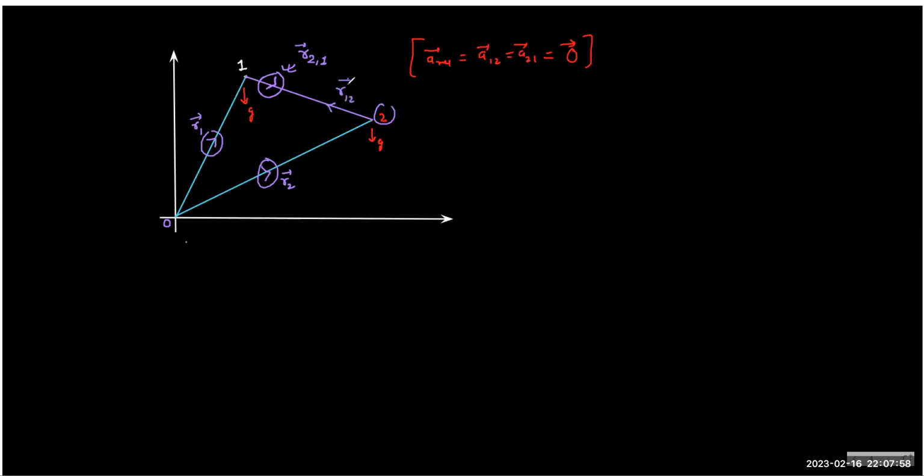I mean, this is not a big deal. R12. So the first subscript goes to the object, the second goes to the observer. So it is always this order, R of object with observer. Do you realize this, what I'm saying? So a double subscript notation is meant for the relative motion. A single subscript is always for the ground frame. So that's simple. And from the triangle, you can clearly see R21 is how much?